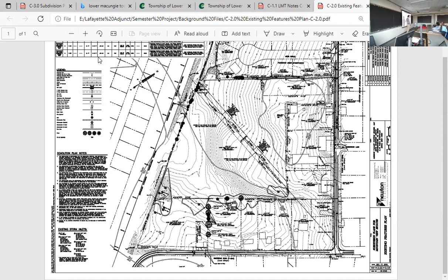Do we think that the road for my subdivision can go out onto the turnpike? Why not? Speed change. It's not that quick. That's true. The style of the road is called limited access, right? That tells you everything you need to know. You can only have so many access points. You'd have to build an interchange.